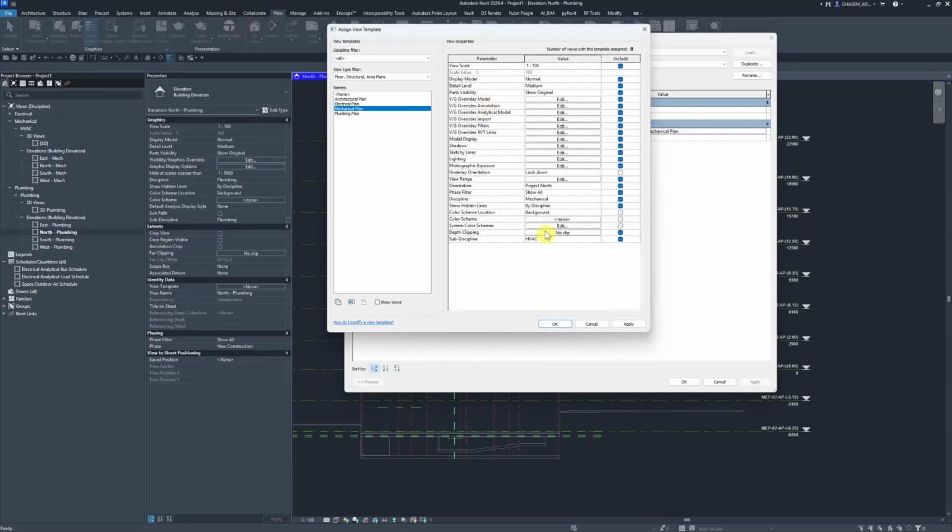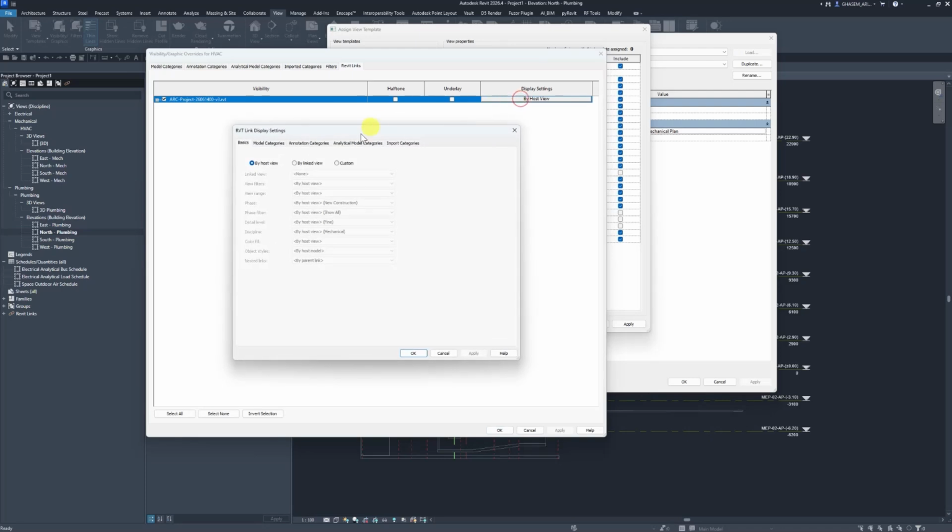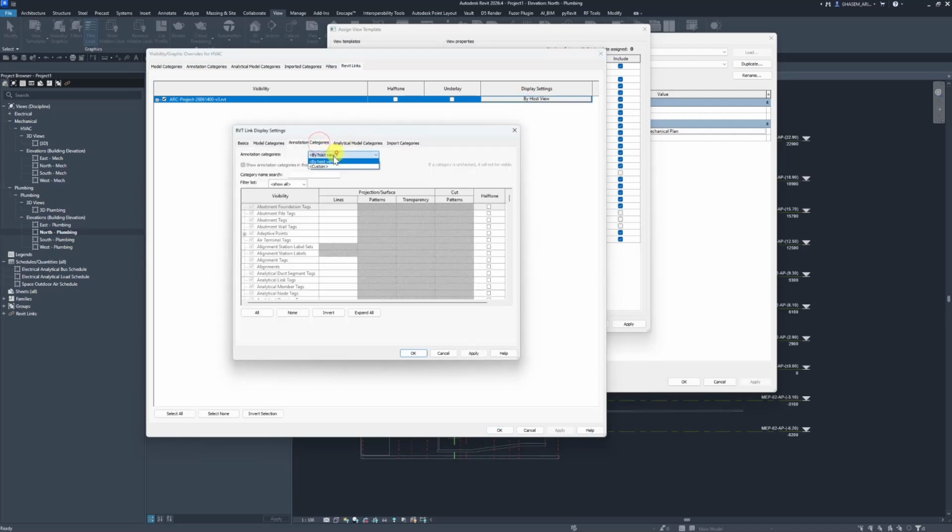Now this is already set on HVAC, but just to make sure, I'll be using another duplicate and try to specify the settings again myself. This will be more precise this way. So, detail level on fine, scale on 1:100. Then, as for the discipline, mechanical, subdiscipline, HVAC. Now, one more time from RVT links, custom again, and here select level.